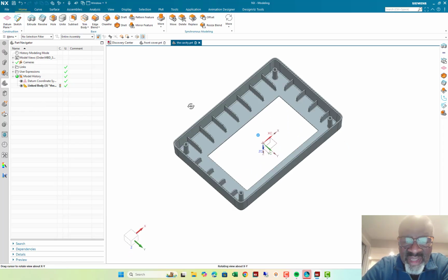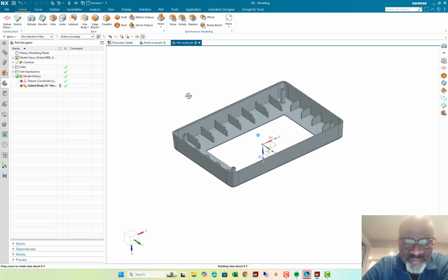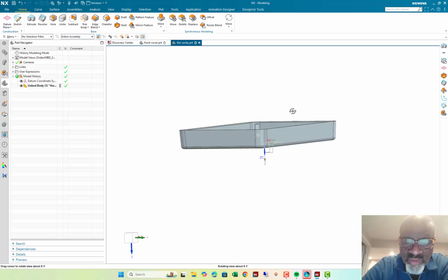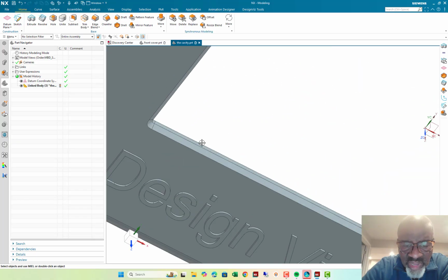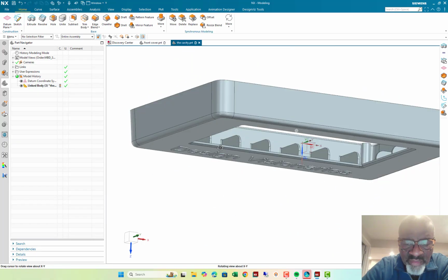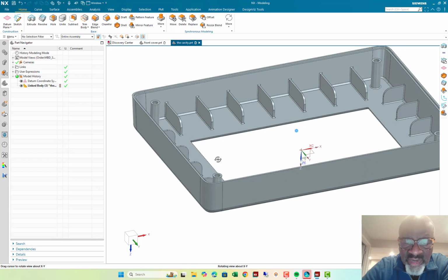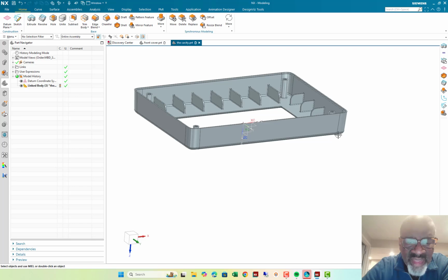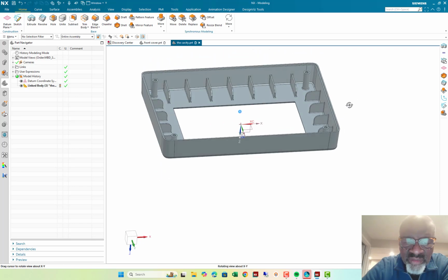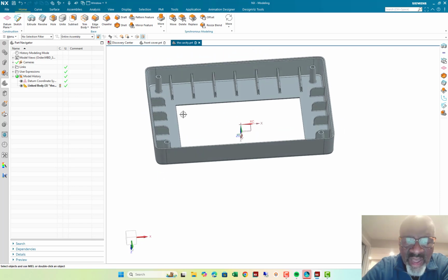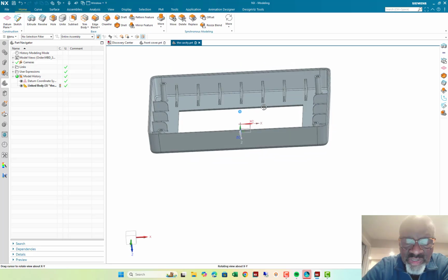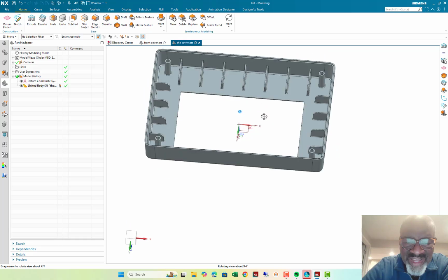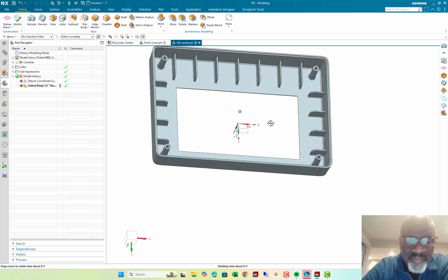And now I want to make the cavity. The cavity is quite simple. It's really just the outside surfaces of this, plus where I want this to shut off, so to speak. So what I'd like to do is create a block that I will use for the mold base, basically, and then operate on this piece of geometry so it is ready for me to use it as a cutter, so to speak.